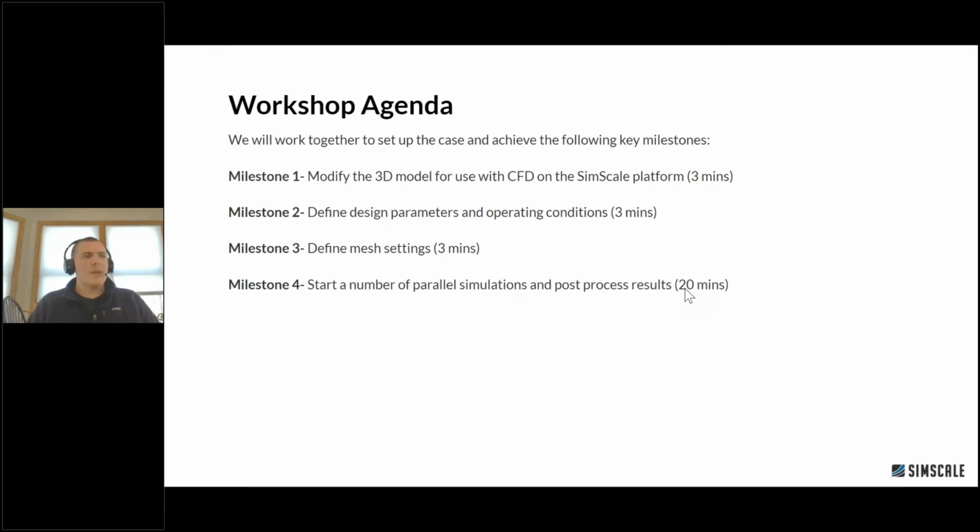Lastly, we'll set up the mesh and go over some runtime parameters. Things like setting result controls, so that once you have results, not just that you have results, but that they are very good and accurate and you can trust them. Lastly, we'll spend a good chunk of time in the post-processor learning how to visualize the solution.